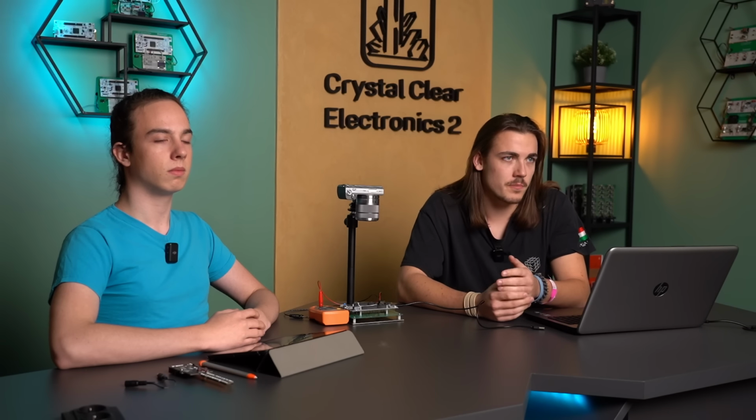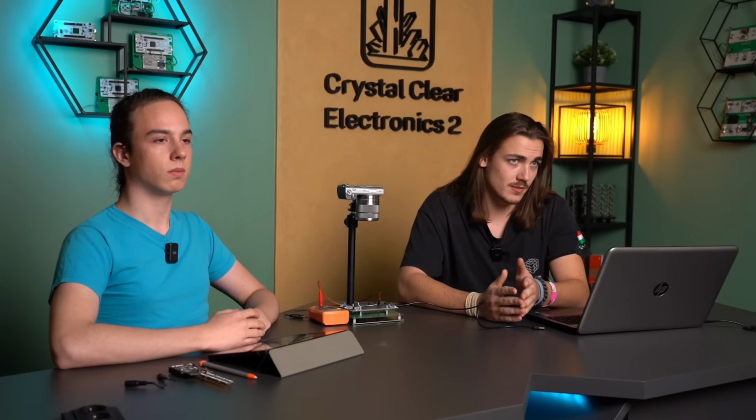When measuring, make sure that the board is only powered via the multimeter. For example, the ST-Link programmer for the Chinese region supplies 3.3 volts, so if it is connected, the measurement will be distorted. The version intended for the global market does not feed the microcontroller via the 3.3 volts pin. It only monitors voltage, which also introduces distortion into the measurement, but that is negligible. To calculate the power, we also need the value of the supply voltage, which can be easily measured with a multimeter, taking care that the rotary switch and the measuring wire are not in the current measuring position.